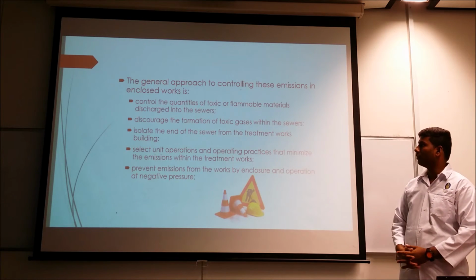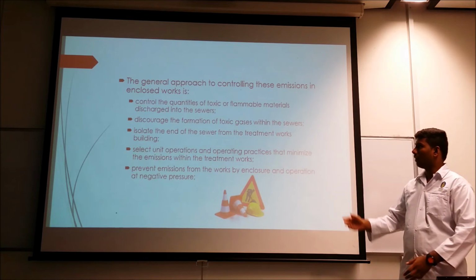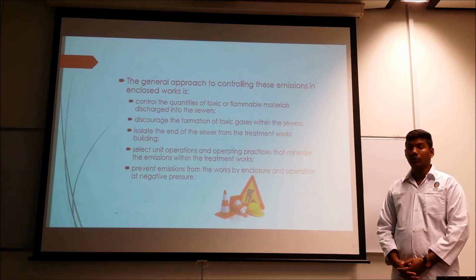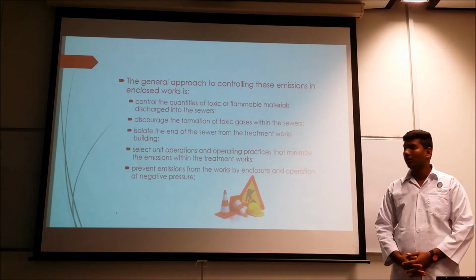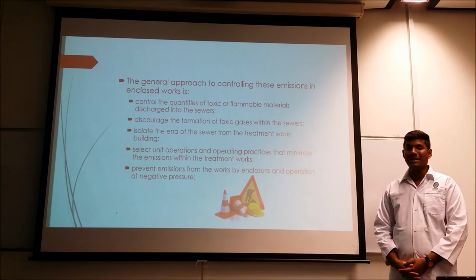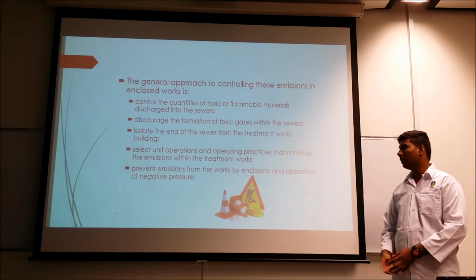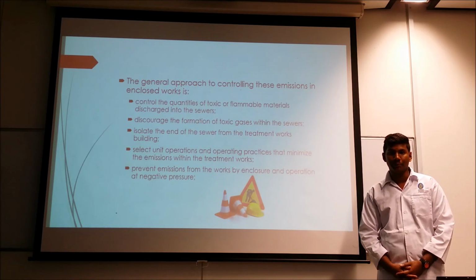First of all, we can control the discharge into the sewers, discourage the formation of toxic gases, isolate the end of the sewer, and also select the unit operations and operating practices that minimize emissions within the treatment works. And last but not least, prevent emissions by enclosing the operation at negative pressure.